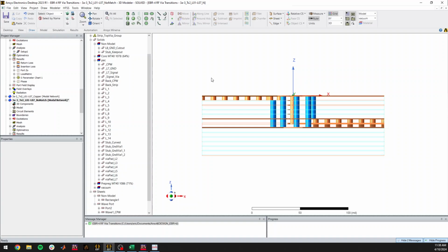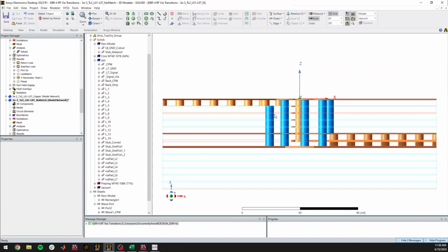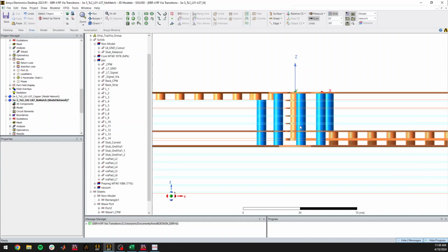And in my case, what I mentioned earlier with the stack up and the via types, we're using laser stacked vias or stacked micro vias. And this lets you very easily, within some manufacturing limit, put these micro vias on top of each other, maybe 5 or 6 times maximum, and go directly from layer A to layer B. So in this case, CPW to the stripline.